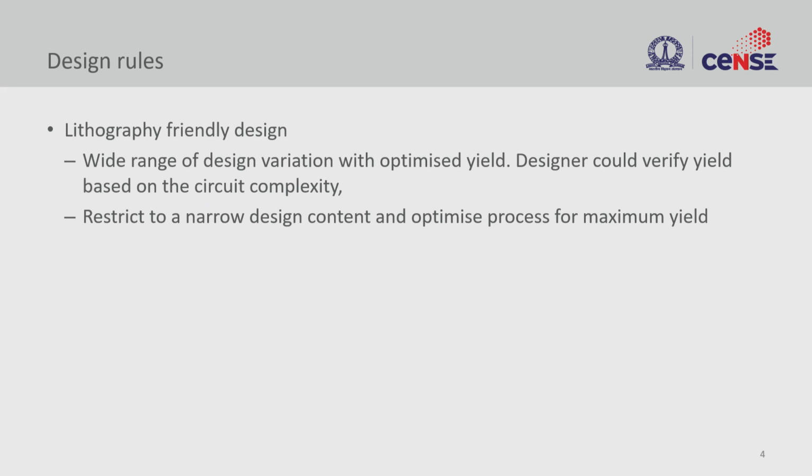The first point in achieving a litho friendly design is following DRC, design rule compliance, right. So design rule check is the first step. If you clear the design rules, then you presume that all your devices will be on spec and you don't have to worry about your yield and so on. But that may not be true. Physically there are certain limitations, and those were used to define this DRC.